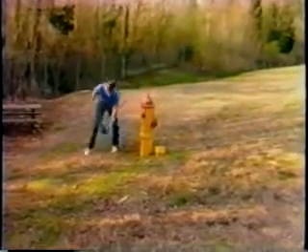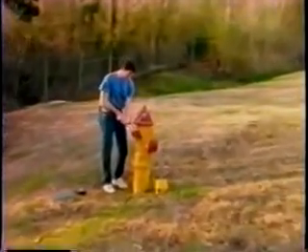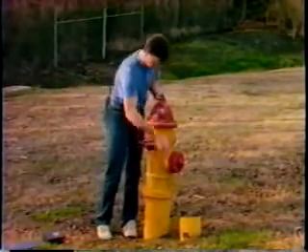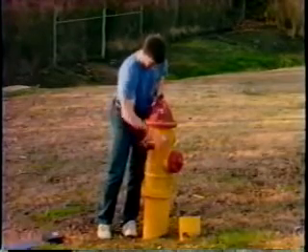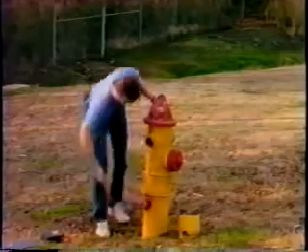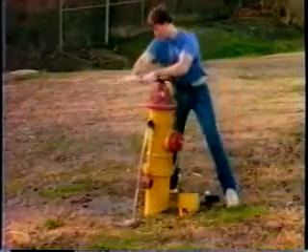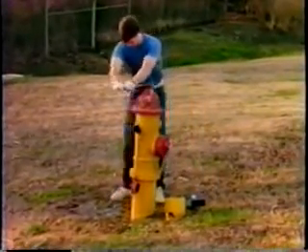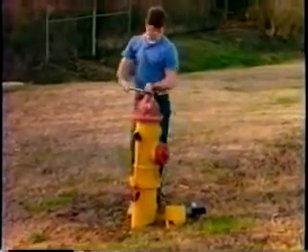Upon arriving at the flow hydrant, the individual who's going to be conducting that part of the test first assesses the area and selects the outlet to open that will cause the least amount of damage due to flooding and erosion. He then removes the cap from the hydrant outlet and bleeds any debris or sediment out of the hydrant lateral and barrel. This is done to prevent any debris from flying out of the hydrant outlet and hitting the gauge and damaging it. It's amazing some of the things that children and vandals will put inside of a hydrant.